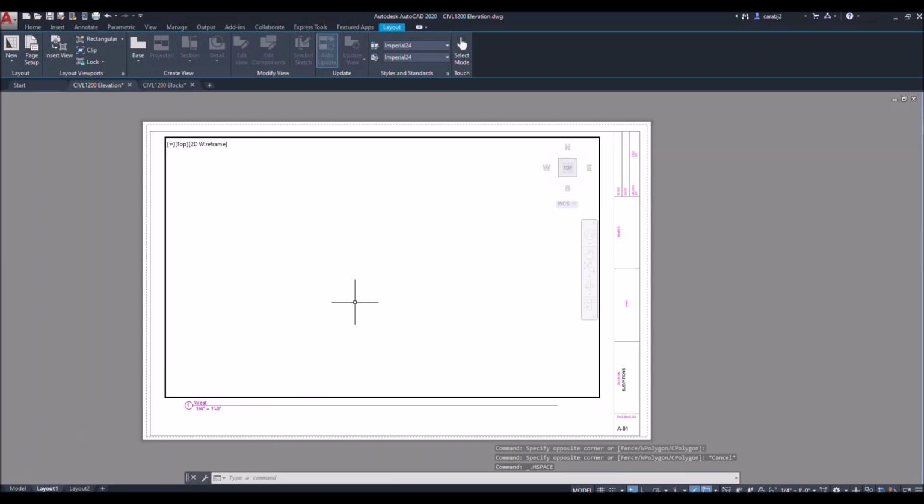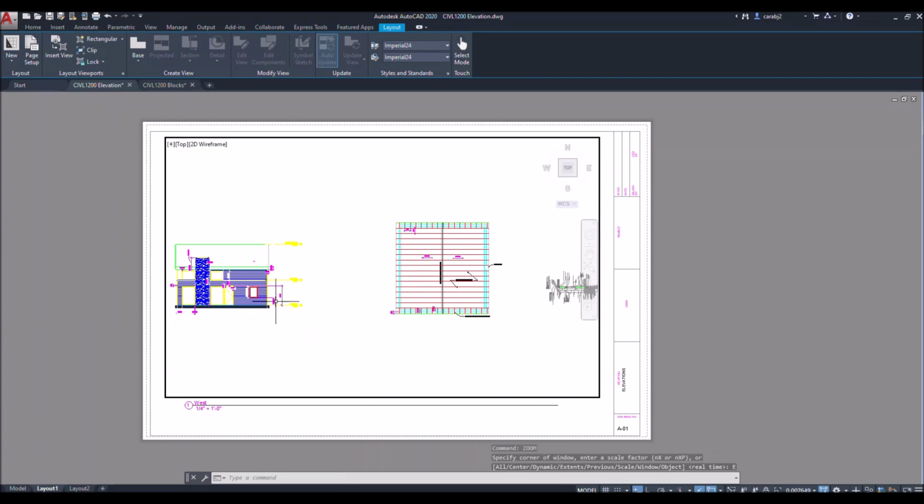What you can just do is double click within your viewport, type in zoom, and then at the bottom it gives you all these options. What you're just going to type in is extents, because that's just going to zoom into your extents of your drawing over your model space. So you can just type in extents. Oh, let me do that again. Zoom, extents, or you can click on it and you can see how it brought you back. But since you did the zoom, the scale changed.